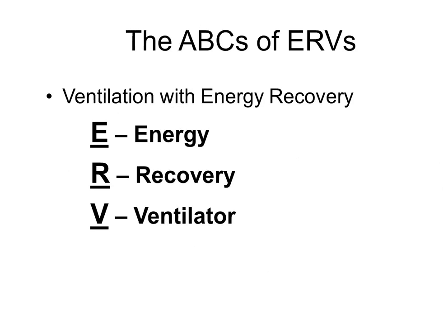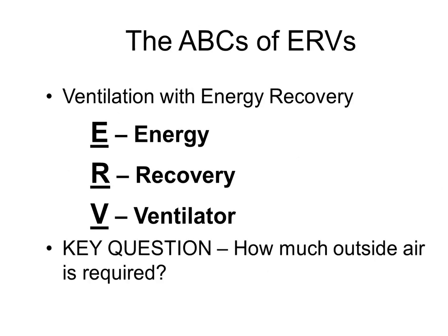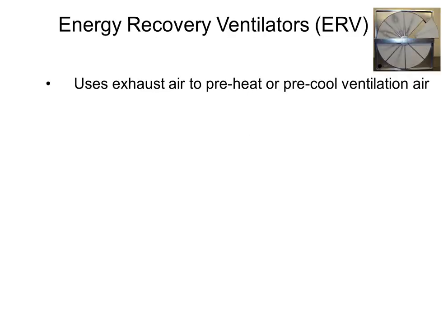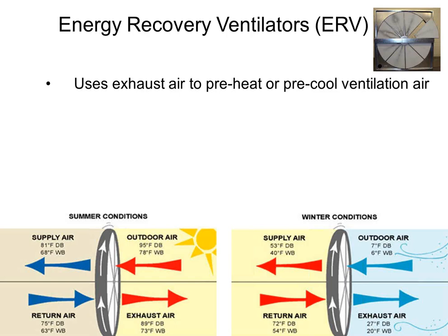So for those who don't know, ERV stands for Energy Recovery Ventilator. The big question we always ask is how much outside air are we talking about? If you don't have very much outside air, there's no point in me trying to do some kind of recovery to temper it up for you. So the more CFM you got, the better. Basically what the ERV does is it preheats, pre-cools, pre-humidifies, and dehumidifies your incoming ventilation air.